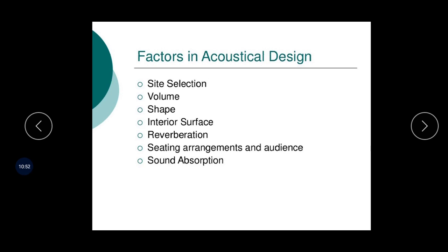So suppose lecture halls are there, the volume per seat is between 2 to 3 meter cube. The ratio of height, width, and length is to be taken as 1:1 to 1.5:3 to 3. Approximate capacity in persons we can say 150 to 300. If the lecture hall is big, the volume is to be taken as 3.5 meter cube. The ratio of height, width, length is taken as 1:2:4. Now how many persons can sit here? 400 to 500. See, size is changed.